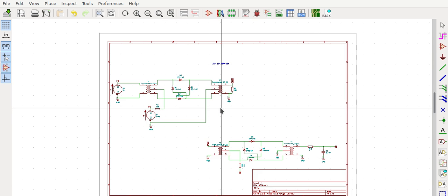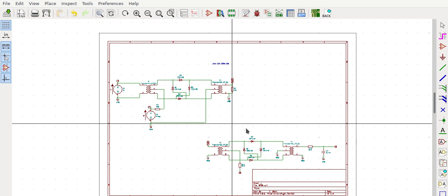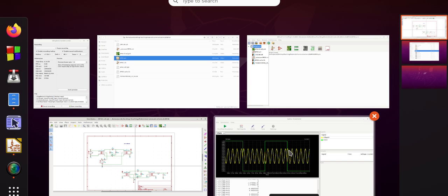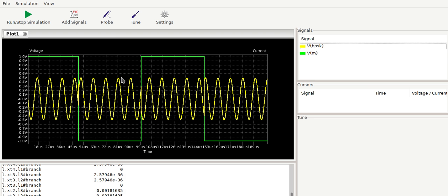And if you take that perspective, then in order to decode this BPSK stream, what you can do is multiply it with the carrier signal itself. During the regions where it is out of phase with the carrier signal, the product will give you a negative voltage, and during the regions where it is in phase with the carrier, you will get a positive voltage.